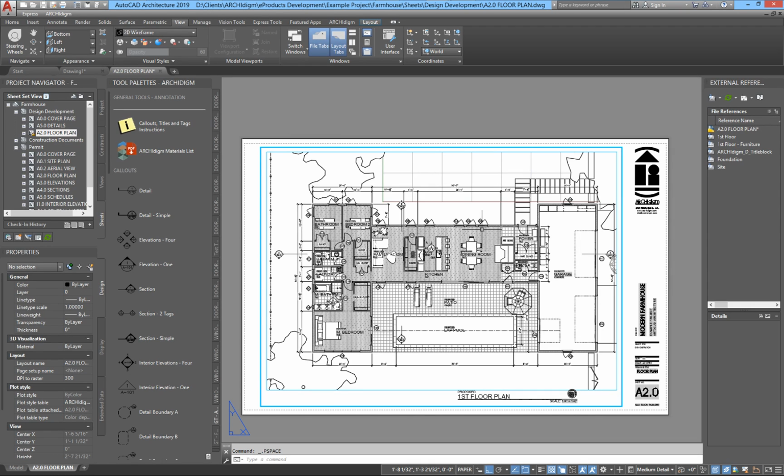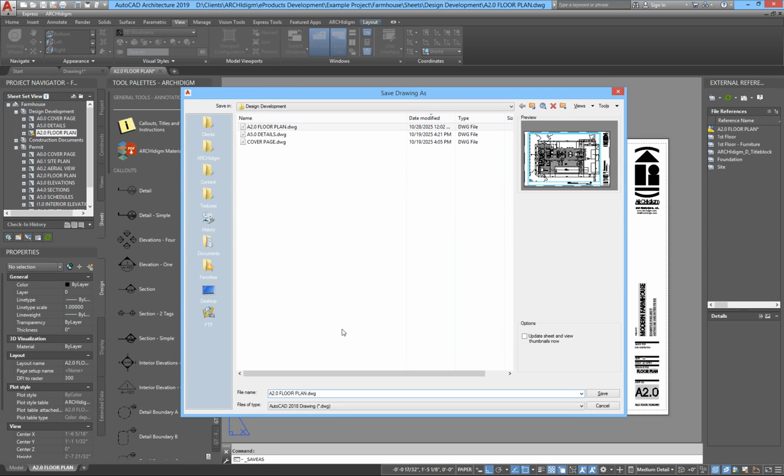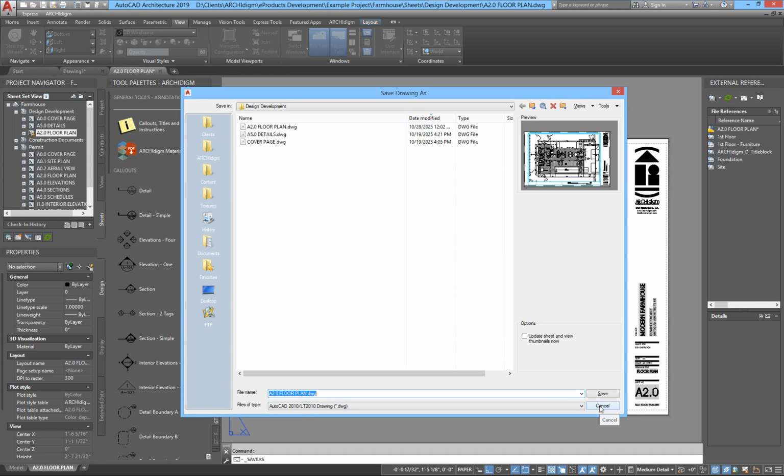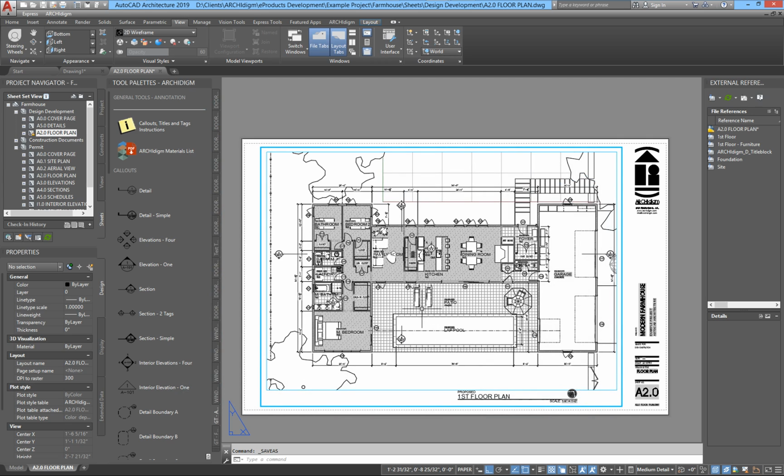If you Google or ask some AI bot about how to do this conversion stuff, I think there's a misunderstanding between doing a downversion when you're saving a file down versus actually converting the file. These files need to be converted. They're not necessarily saved down. So if you go in here and go to Save As, and you knock it down to a release earlier, let's say 2010 or something, that is not going to convert the file. It is downverting, saving it down to an older release, but it's not converting it to just pure DWG stuff.